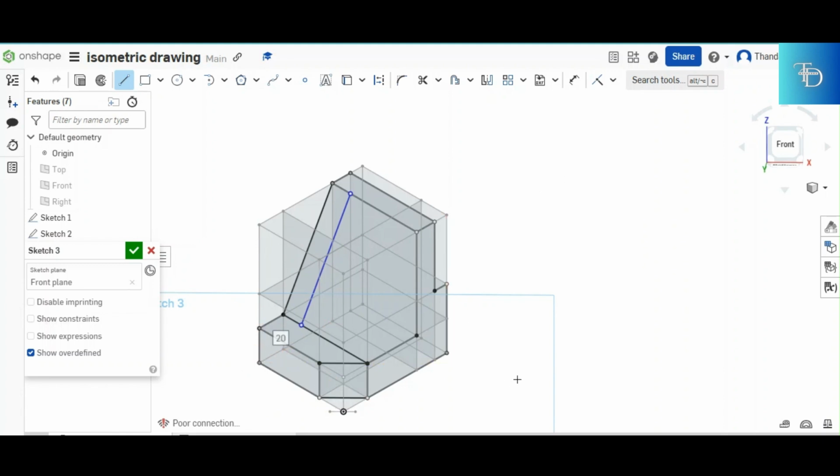Now you're almost done with the drawing. The only thing that is left now for your drawing to make sense is to complete that area right there. Now, since this is the 3D part and everything is welded together, the next thing that you do, you take this point, you throw it to that direction without measuring anything, and then you come back to this point right there, you throw it to that direction, and I guarantee you those 2 points will meet at that vertical line right there, because everything was done correctly and accurately. Those 2 points should meet exactly at that line right there. So now let's see if everything was done accurately.